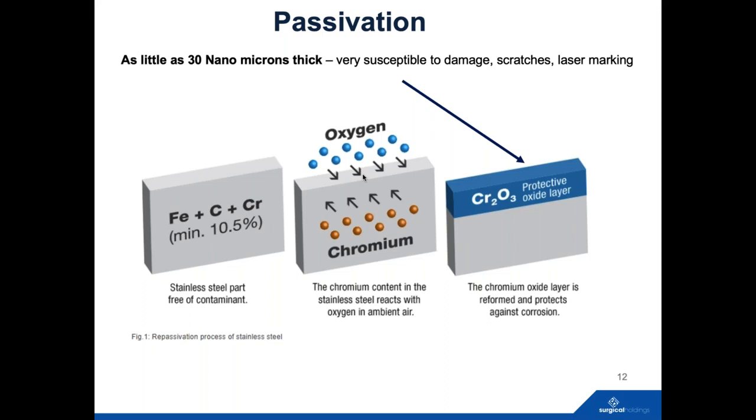There are modernizing machinery for laser marking all the time. That area is improving all the time. There are processes that don't actually need too much passivation after laser marking nowadays, and in situ treatments that can be done to reduce that. But as a rule of thumb, if the surface of the steel is damaged, then obviously you have the potential for the iron to leach out. And if we reflect back to our image of the piece of iron ore, to understand that.